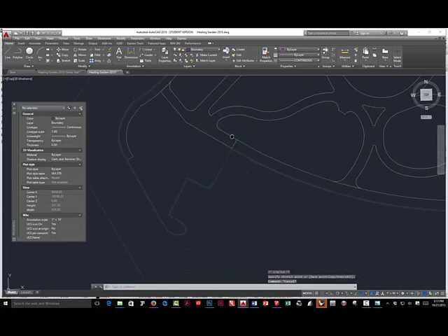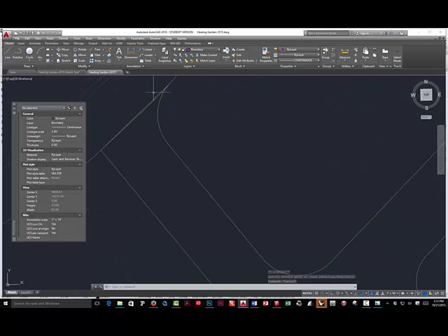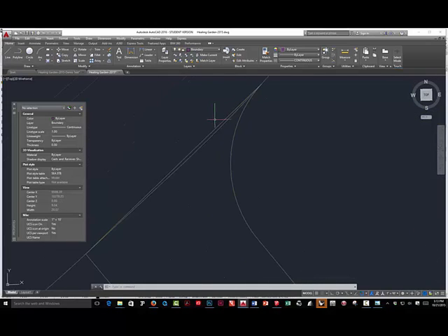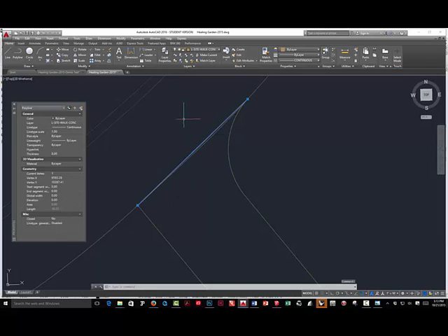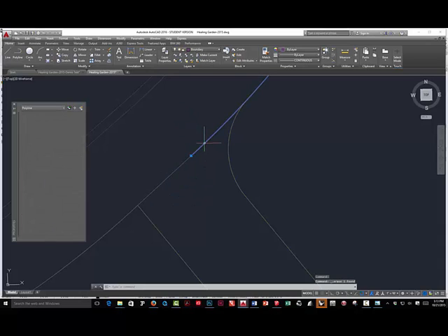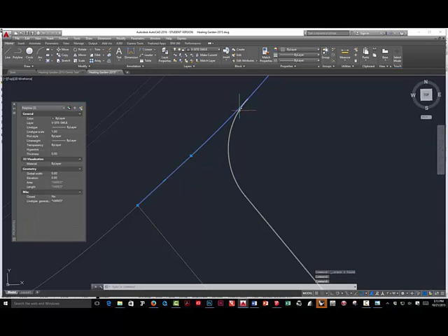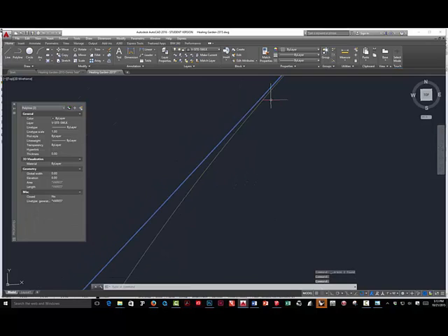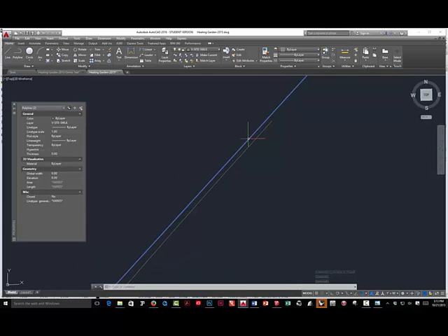So if you do your drafting properly, okay, here's another example. There's two edges here. One's for the existing and one's for the proposed walk. I don't really need both of those, so let's pick one, just delete that. So this line runs through and it still connects right into this one. Well, it should.